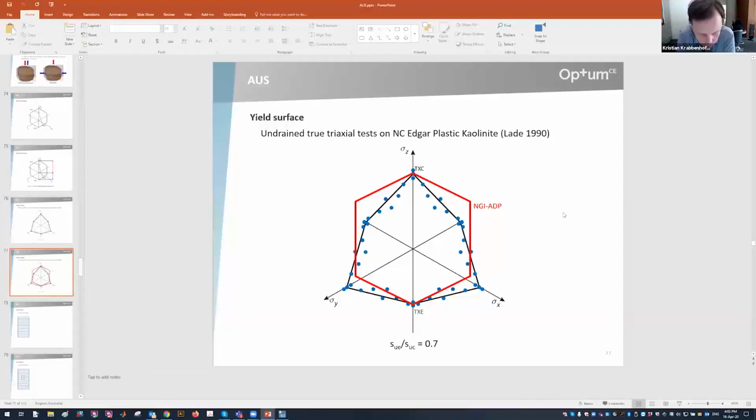The main difference between the two programs is user friendliness, especially when it comes to robustness of the calculations, both in terms of convergence and in terms of actually getting accurate results, and the ability in Optum to verify the accuracy of your results using the upper-lower bound methodology that we have talked about in previous webinars. All in all, I think that gives a much quicker workflow, and in engineering practice it would give quite a significant boost in productivity.